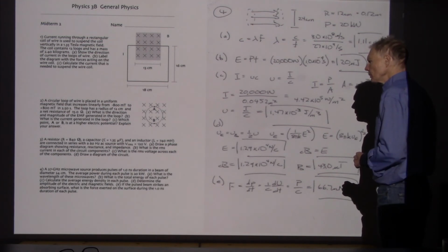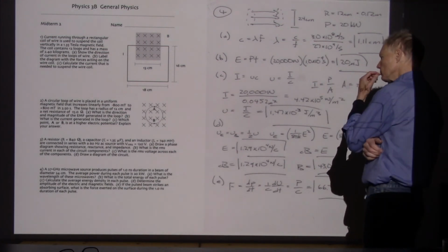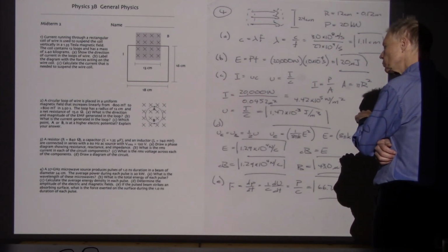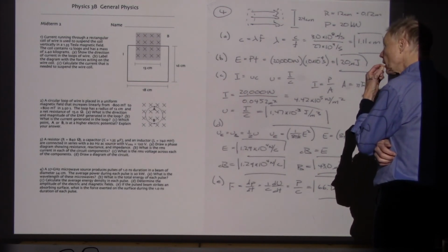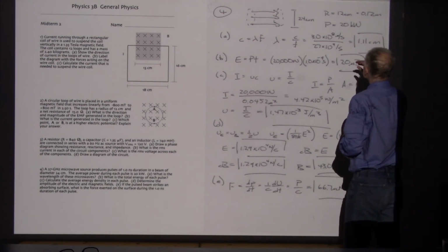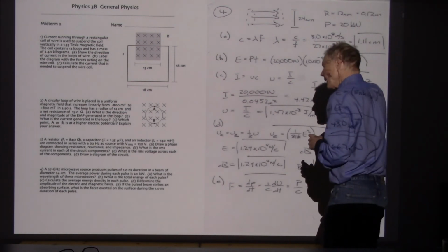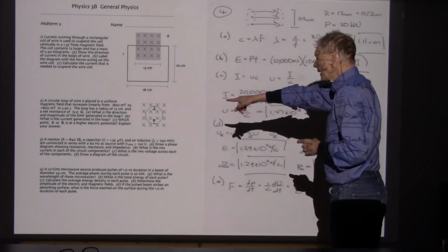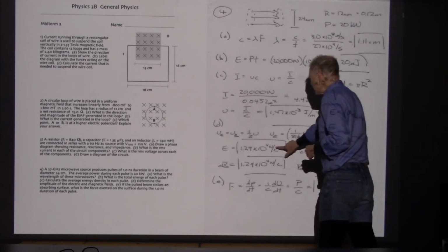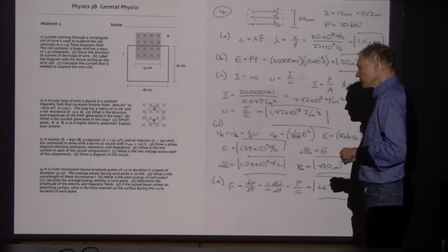Now, let's see. The default understanding here would be that these would be the peak fields, huh? Because we didn't really do a, oh, I think we did. I think we did averaging. So as far as the power here, it would be an average power during the 1 nanosecond, and it said that. The average power is 20,000 watts, and that means that these are RMS fields. That's an RMS electric field, that's an RMS magnetic field.